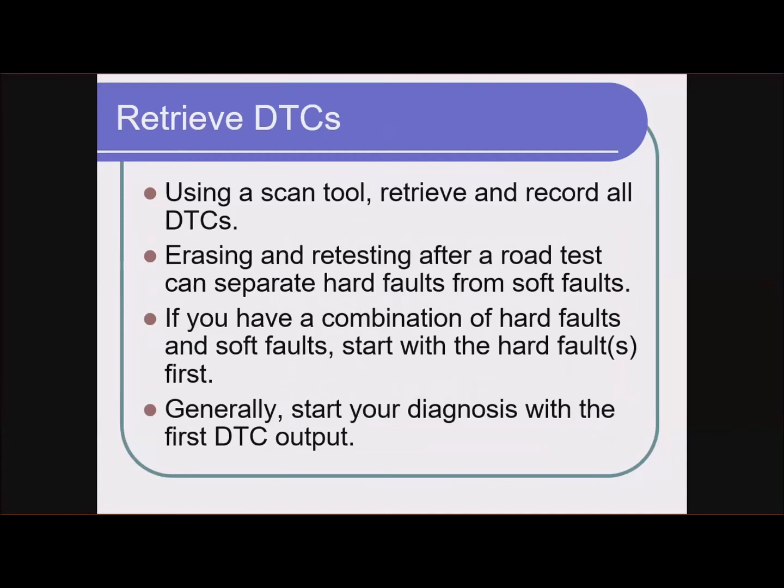So next, and this has changed over the years. When I was working in the dealership, and that was a long time ago, diagnostic trouble codes were the very last thing that we ever looked at because the onboard diagnostics were bad. They were kind of primitive. So they could be fooled very easily by mechanical problems. Still run into this occasionally, on more modern cars.